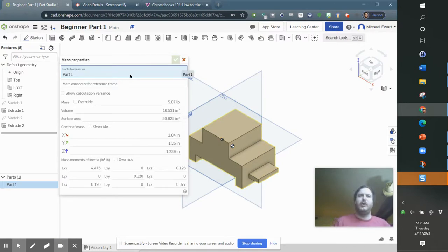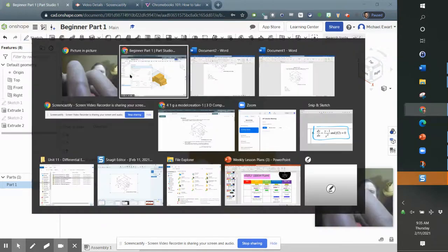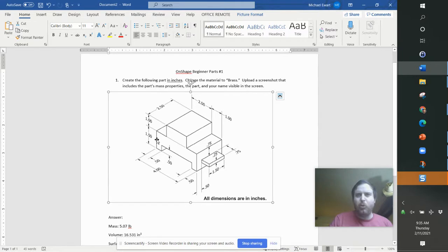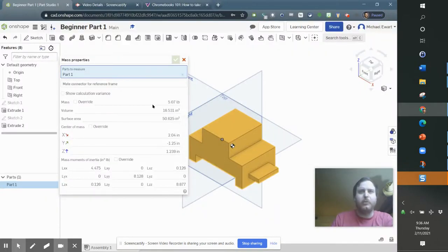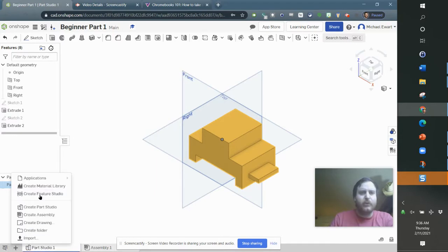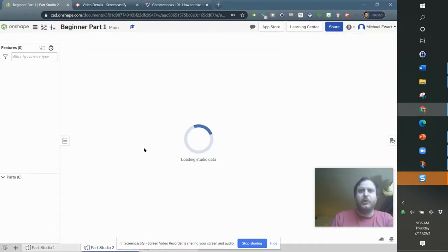You could do this with the subtractive model as well. I'm not going to go through all of that, but on the subtractive model, what you could have done is make one really big box around everything to start. And then you could have cut out the top left square, the top right square, and this bottom rectangle. I can show that really quickly. It won't take long. You don't have to do this, we already made ours, but just so you could see it,